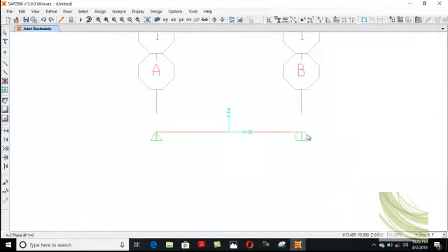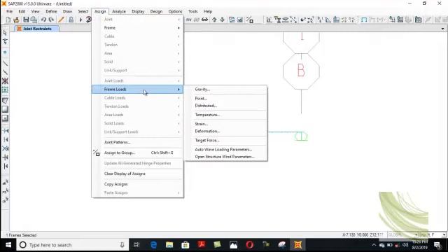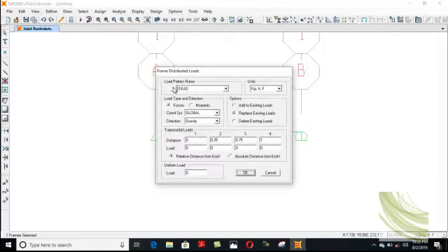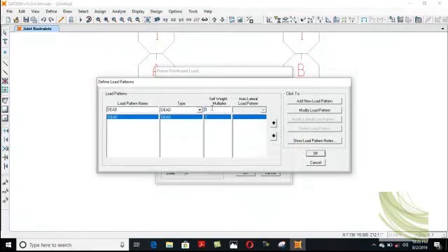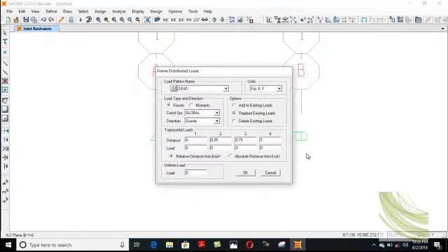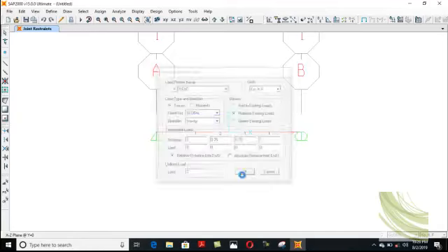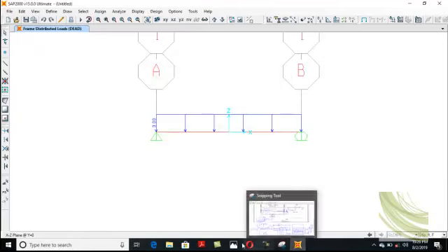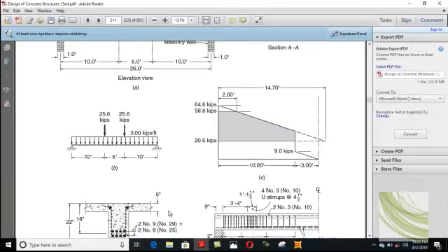Because the span is so high and the loading is so high, those beams just don't work like a fixed support. Clear? So let's see. We assign the frame load that is distributed, and as we calculate the self weight, taking self weight multiplier equal to 0, and we have 3 kip per foot loading. Okay, this is 3 kip per foot loading. And we also have point loading.